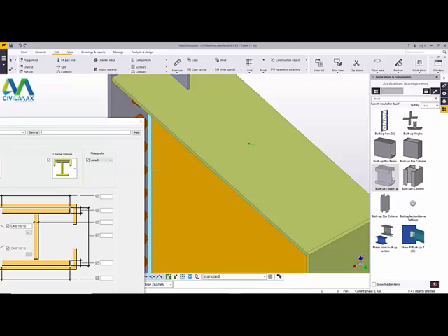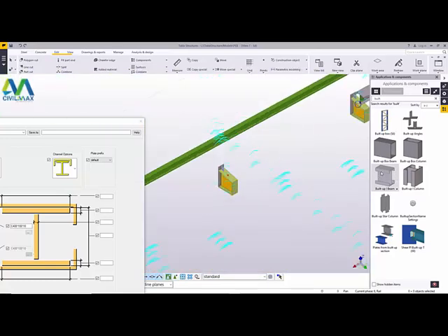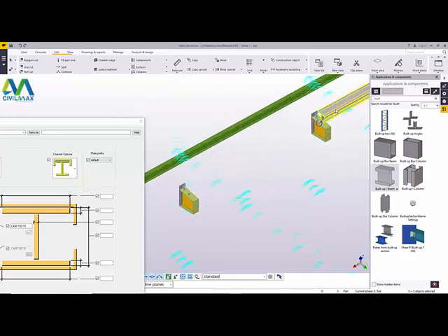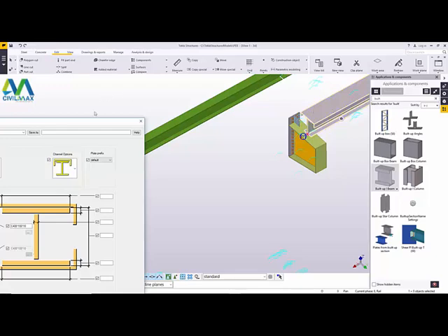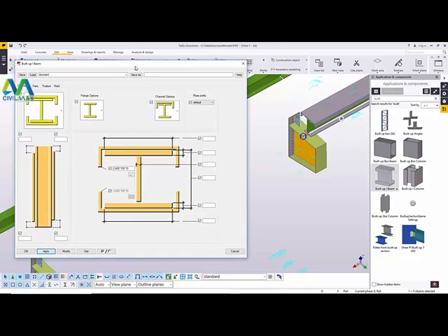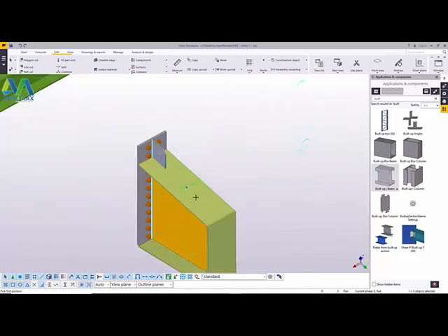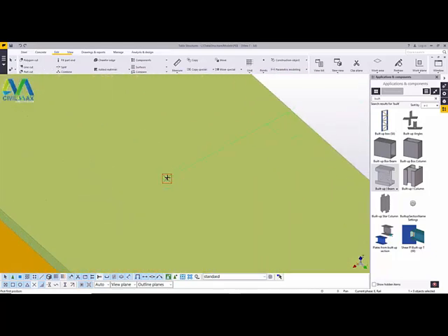Now I want to place my girder, and to place my girder, I don't want to go there and start setting or feeding the dimensions or customizing further. What to do, just double click on the existing and click modify, apply and accept by clicking on OK here, and that will reactivate your previous settings to be a default to a member you were just about to create. Now I'll come back here and click on that and snap at the midpoint here.